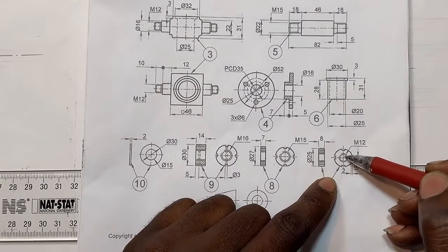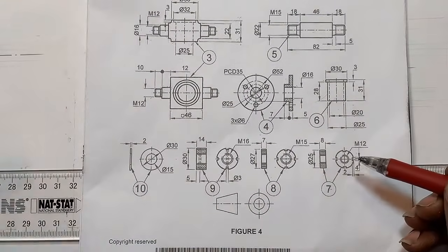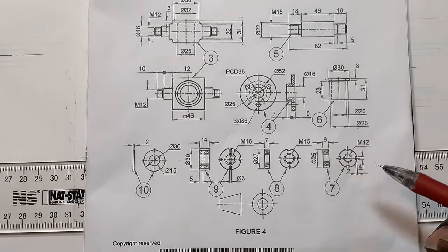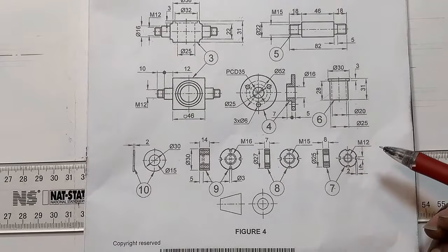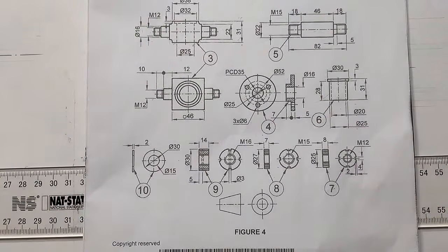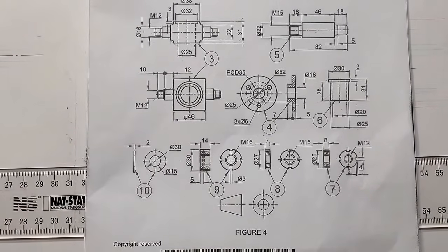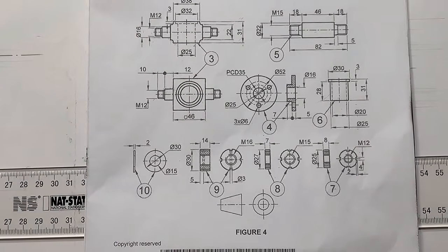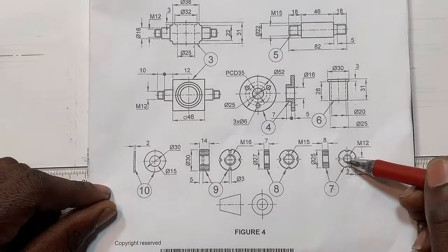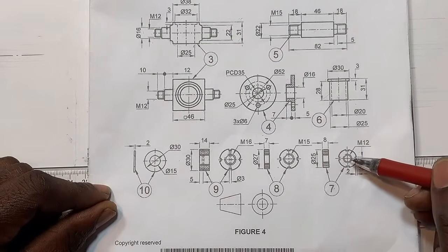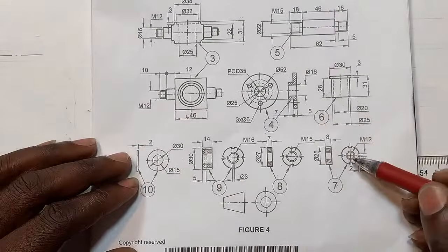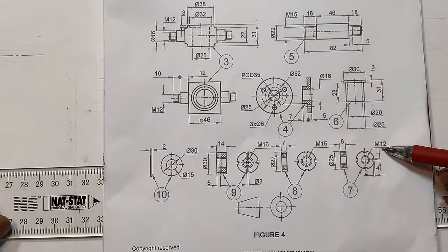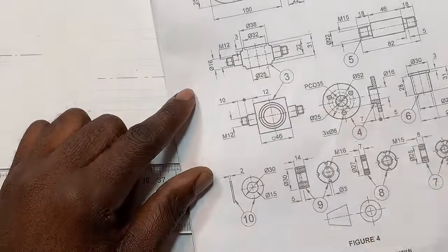So it has got internal thread. Where do we find internal thread? We find internal thread in a nut. If you did your engineering drawing N2 or your grade 11 EGD, where we draw screw threads, internal and external, V screw thread, square screw thread, you understand? Okay, so if it's like this, my brother, it simply tells you it has got internal thread. So these ones will be screwed there. So it's M12, corresponding with your item 3, M12.